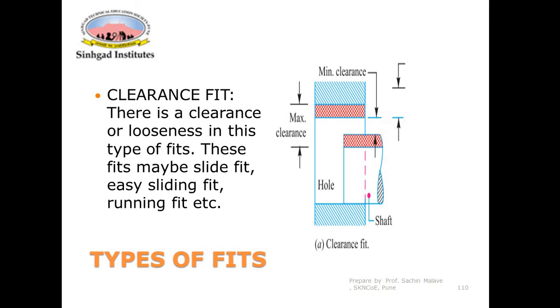So the minimum size of the hole is always greater than the maximum size of the shaft. If this condition is satisfied, then it is called a clearance fit. Okay, this is a clearance fit.